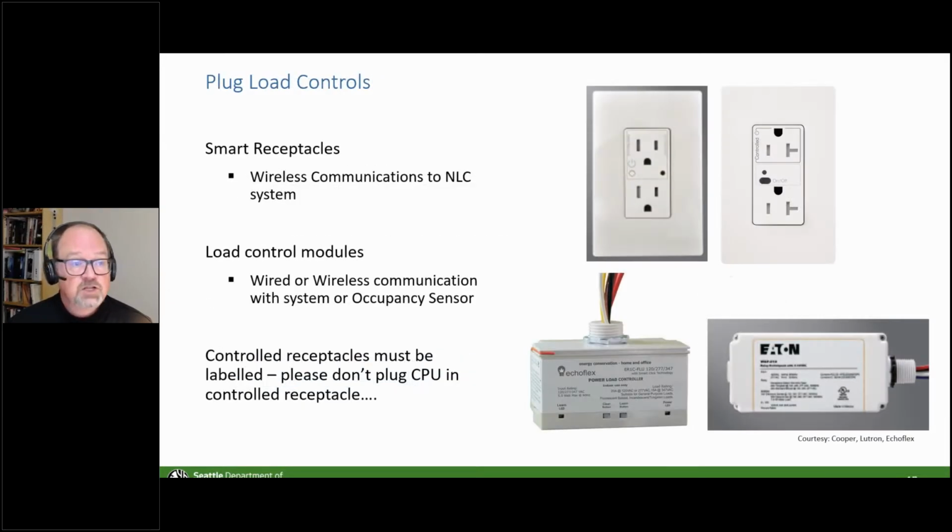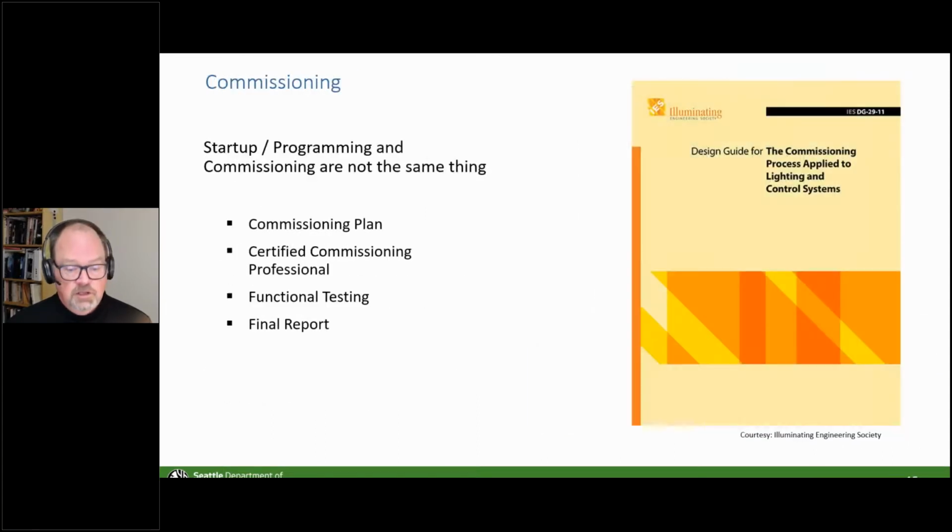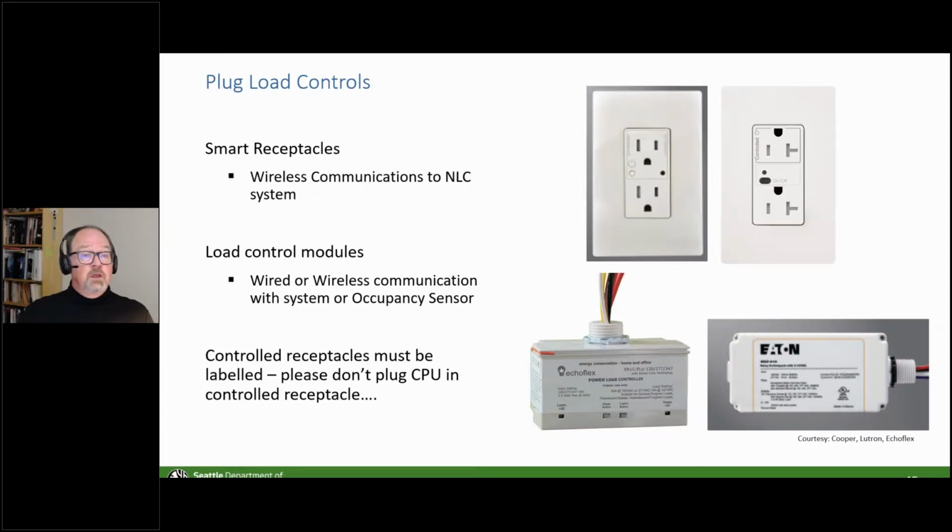Now, Duane had mentioned that one of the things that is out there with respect to the code is the plug load controls. Now, of course, this is not new, that we need to control 50% of the outlets. So a couple of good ways to do that.